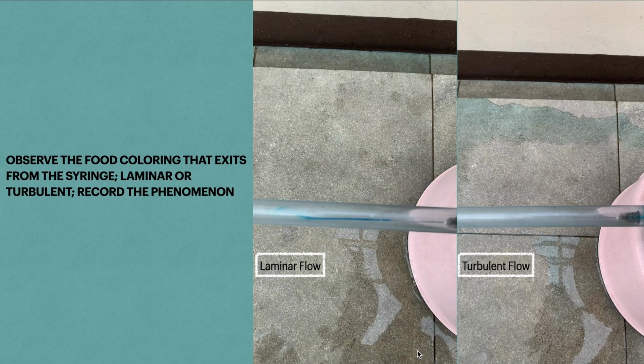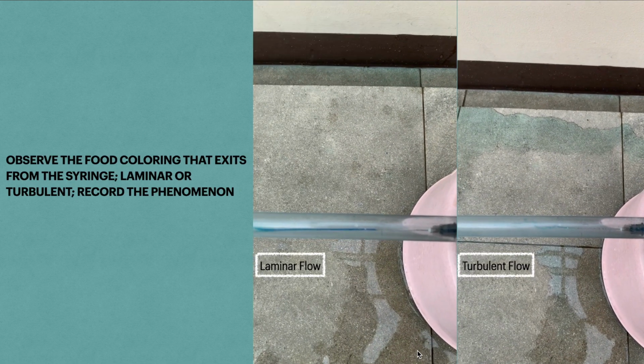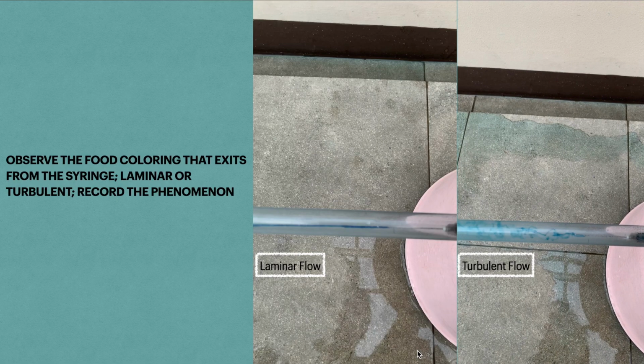After the valve is opened and water starts to flow, inject the food coloring into the flow. Previously, to prevent the food coloring from diluting into the water, stop the flow on the infusion set so that no food coloring can exit the syringe. Now, start the flow and let the food coloring flow with the water. Observe the phenomenon that occurs here.